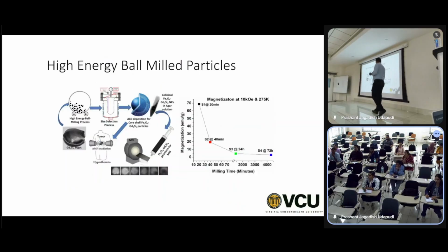So now, what do we want to do? We want to first make powder of it, right? To make powder, first you have to make the material, a gadolinium silicide ingot. Basically put gadolinium and silicon, heat it up to 2500 or 2600 degrees, that is the melting point of gadolinium, and silicon has a slightly lower one. So when you heat it up, both become liquid. It's called arc melting, right? You use an electric arc to melt.